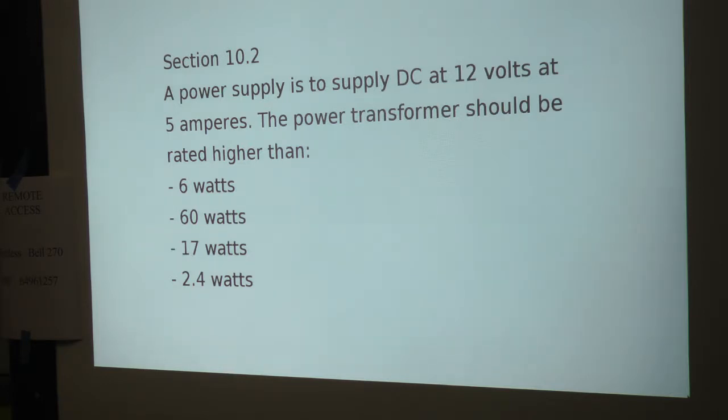Not always. Electrolytic capacitors are submerged in a fluid inside, and that fluid slowly evaporates or leaks. Some power supplies may be poorly designed and put electrolytic capacitors near heat dissipators, like the fins you typically see on devices that produce a lot of heat. You'll typically know very quickly if that's going to cause a problem. But over long periods of use, an electrolytic capacitor can eventually break down and die out. Any other questions?